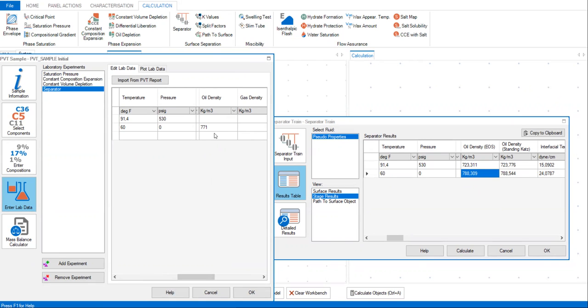All right. And the same can be said of the calculated first stage GOR, which for the model gives us 5,995.56 SCF per STB. It compares quite well with the value written in the report, 5,919 SCF per STB. And the difference is only 1.8%, which is well below 10%. Okay, practically speaking, it is arguably an acceptable match.